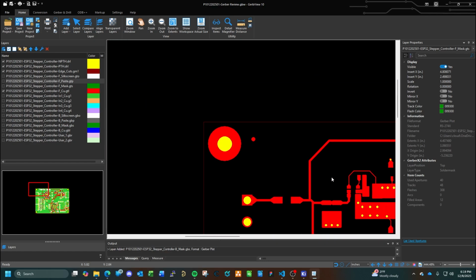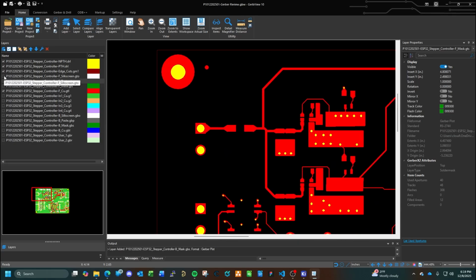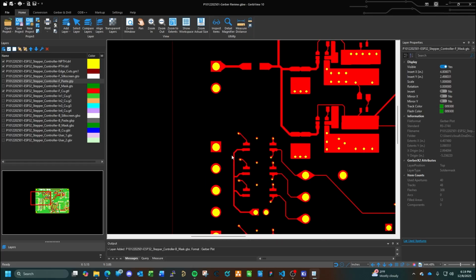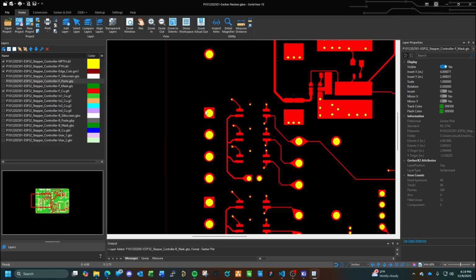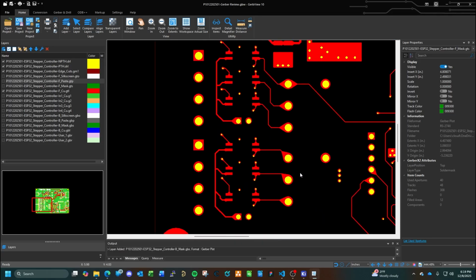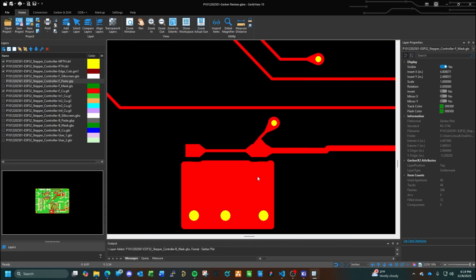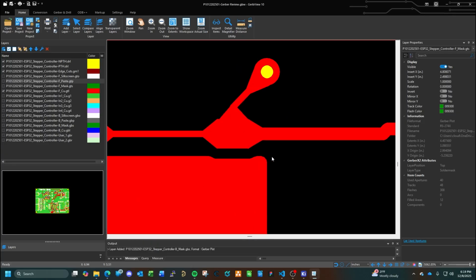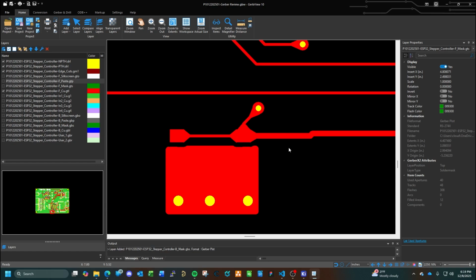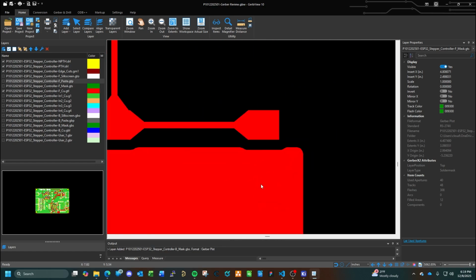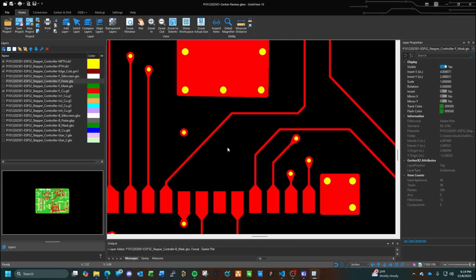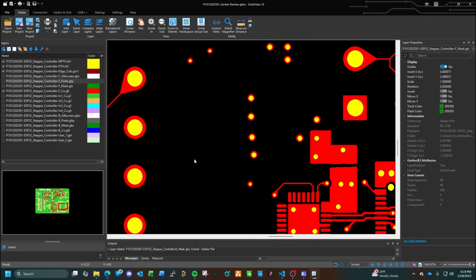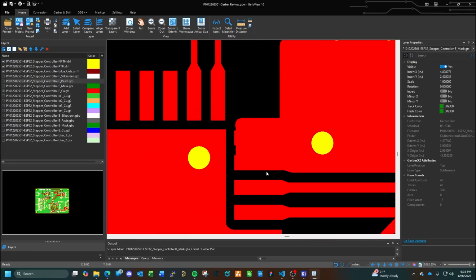So there's a fiducial right there. Again, we can go here, make sure the mask is open for it. Yep. So yep, we can do that. Make sure those are through-hole pads right there. You can tell by the drill marks. Those are vias. Everything looks good. For really complex or high density boards, a check can take quite a bit of time. But for general, you just want to make sure that nothing's shorted out, you don't have any erroneous copper left behind.